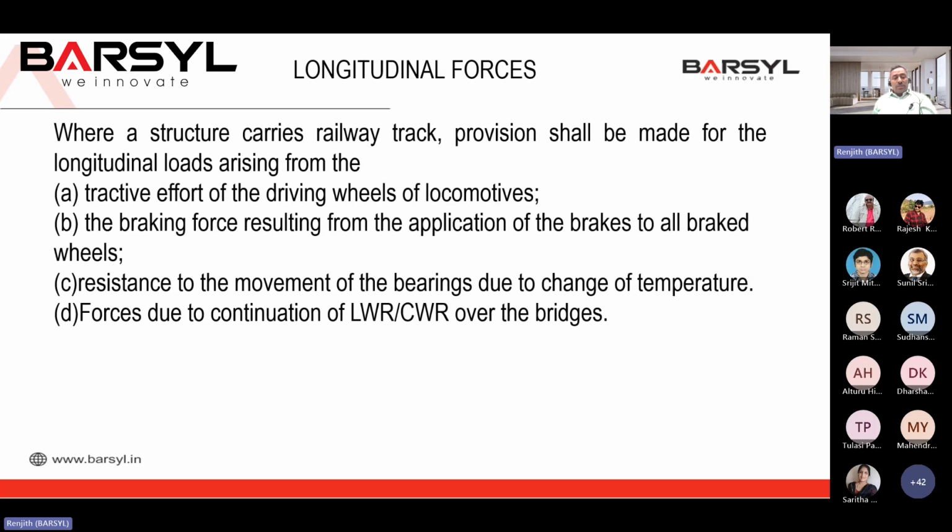Now, longitudinal forces. Longitudinal forces, both in road and railway, include tractive and braking forces. We have to take them into consideration. Tractive effort is there when a train is on the bridge at rest and starts from there. There is a tractive force, and when it is moving and stops, there is a braking effect. How much load is to be considered for the tractive force and for the braking force depends on the span of the structure we are dealing with for the analysis.